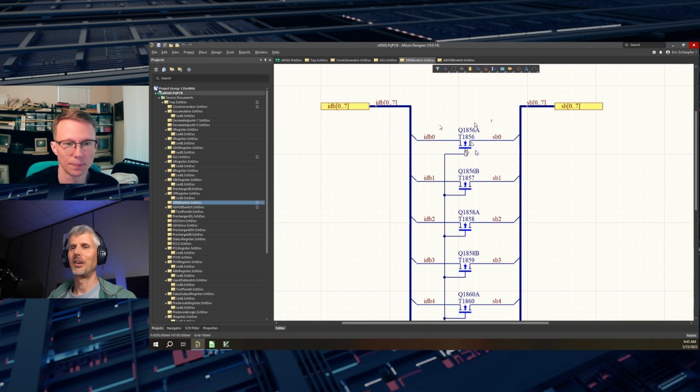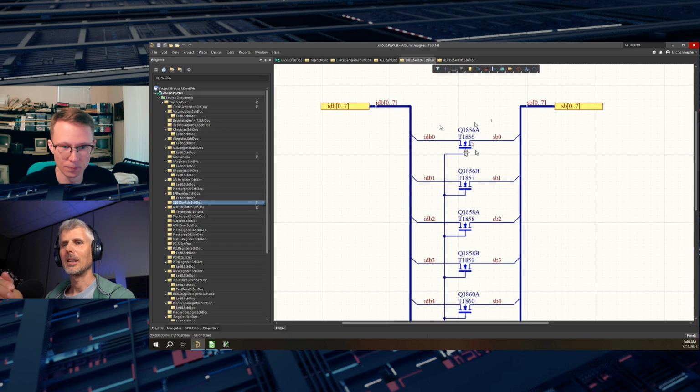And your traces are centimeters, not microns. Exactly. So there's a lot more parasitic capacitance on the traces. This is a 4-layer board, and I have a ground plane. And so, yes, every trace has quite a bit of parasitic capacitance as well. Were you able to calculate that and take it into account? The trace capacitance, I didn't bother calculating because it's swamped by the capacitance of the MOSFETs. So both the drain to substrate and the gate to substrate capacitances.